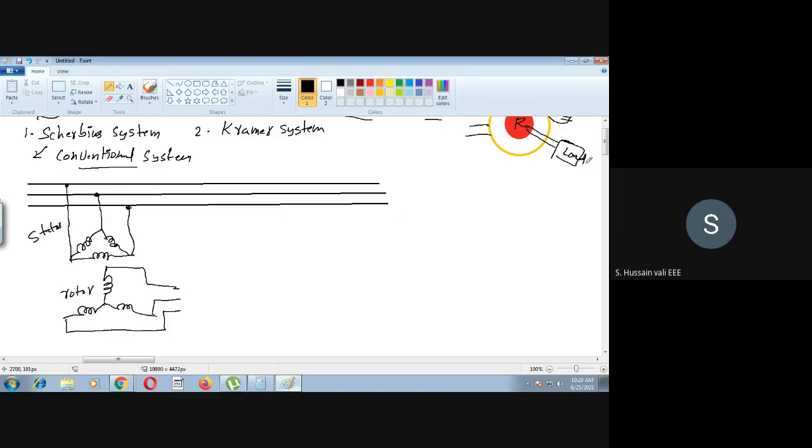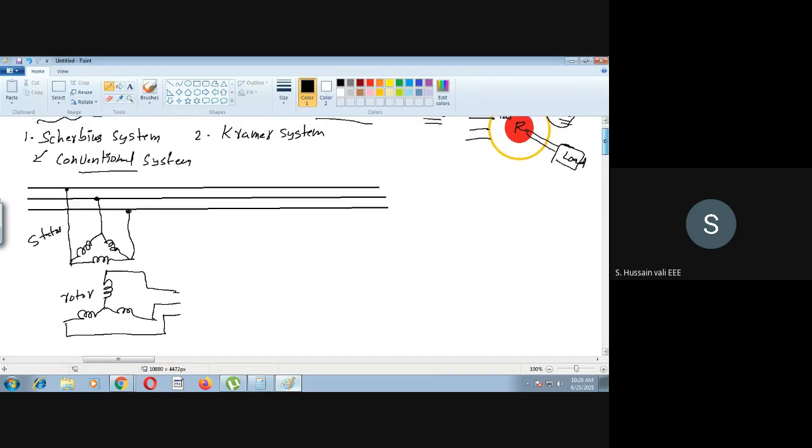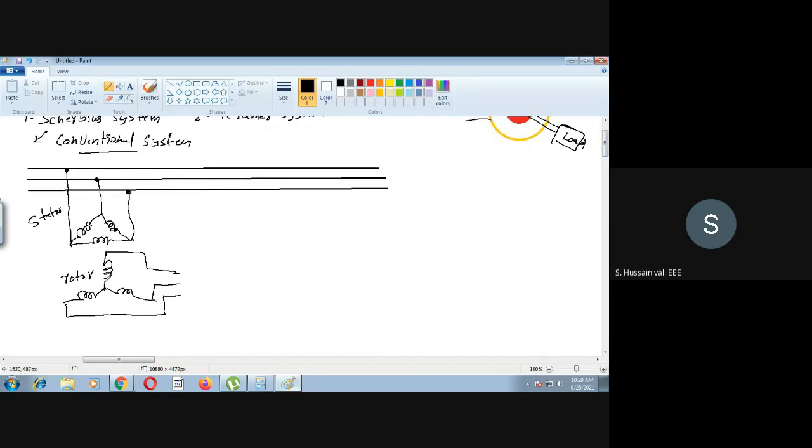The rotor power. Now we are discussing the recovery of the slip power. So we will not worry about whether we connect the load or not. The mechanical load part I'm not going to draw. I will draw only the rotor side part, that is the electrical circuit. So this rotor is connected to one converter. That converter you call a rotary converter.